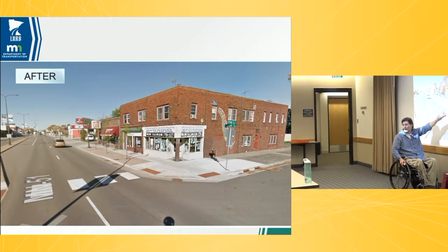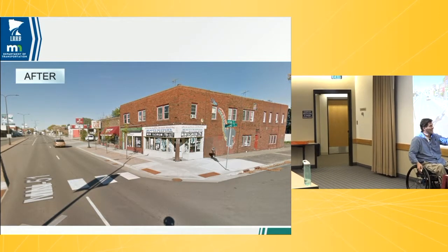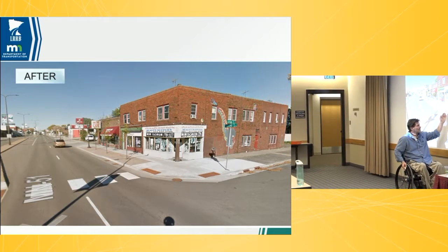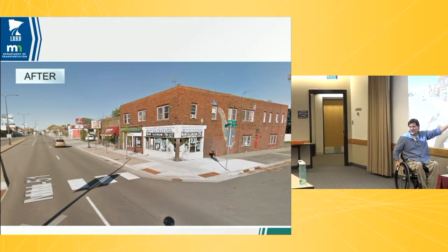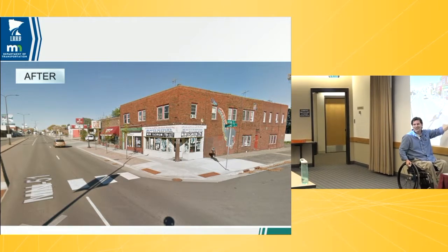So this is a high point, so I can start floating this. We raised this curb line because we had to tie into those doorways. Again, we had the mill and overlay that allowed us to do this. And also, this is kind of the early days of that compound radius. We held tangents through the curb ramp, which was good, it maximized the ramp runs. But there was also this drainage structure in the way, so out of a matter of necessity almost, we just put this straight line chamfer through there.